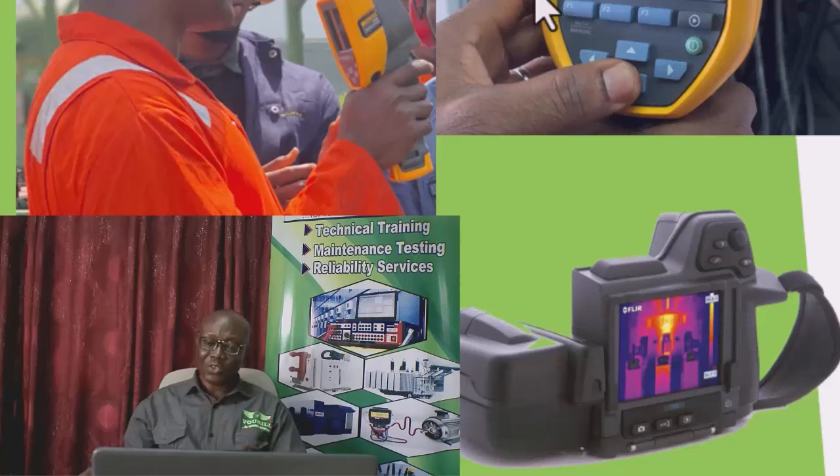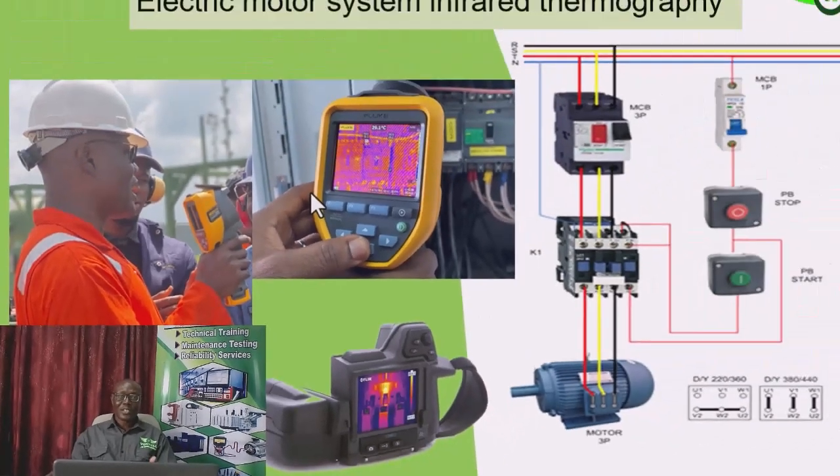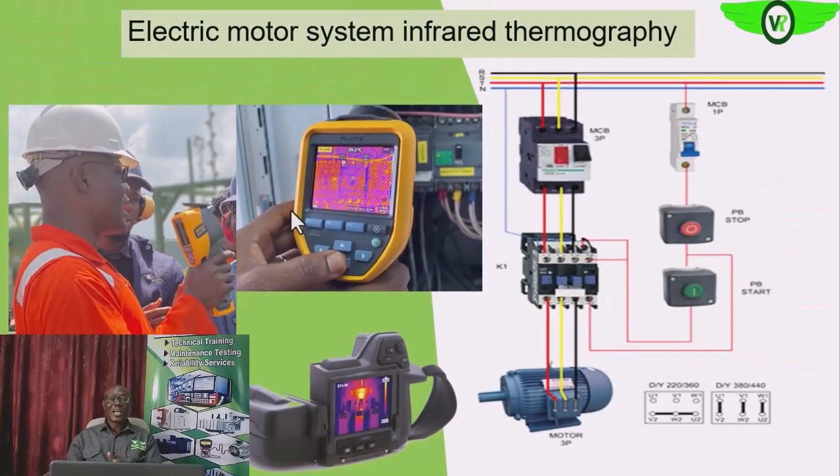So what can cause such resistance buildup is what we need to check. And remember, those resistance buildups can introduce unbalance in the system, and unbalance can increase the heating of the system and reduce the integrity and reliability of our electric motor system.